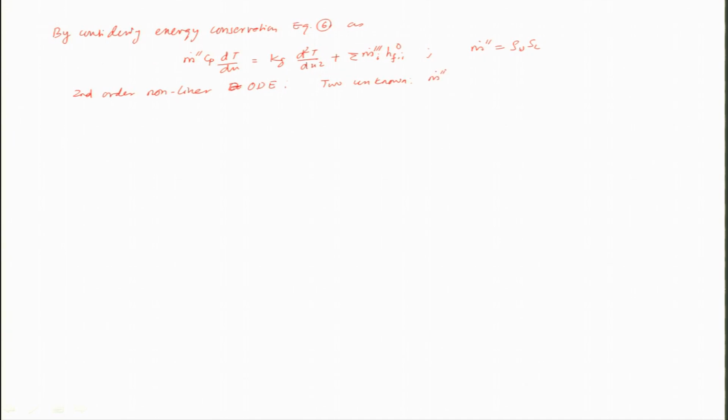One is mass flux is not known. Of course, you do not know the temperature, but we will see how to, and we will also find the flame thickness, which is not known. It is similar to your boundary layer theory, where you have two unknowns and 4 boundary conditions have to be satisfied, and it is an eigenvalue problem. So, you can look at this: the eigenvalues are m dot double dash and delta, the flame thickness, right. And we will be looking at basically solving this equation.